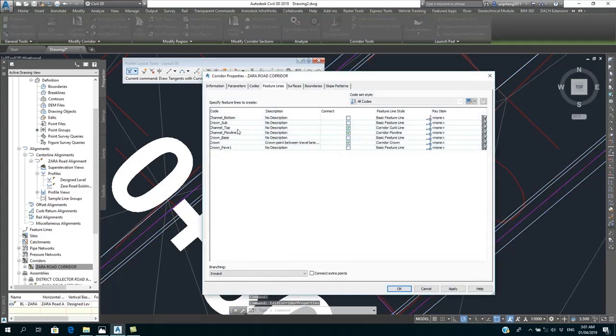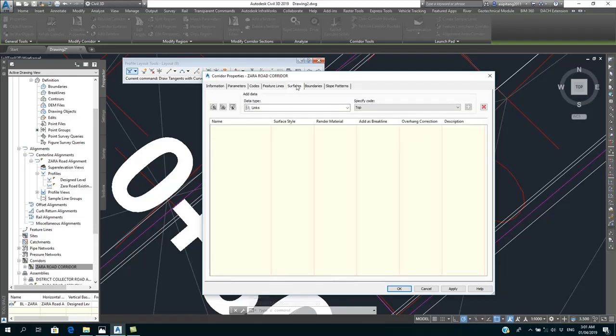While the end of the wall, if you say end of shoulder, you should not show the details, can show other details as well. So now after that, I can come to surface. You must create what we call the corridor surface, and you have to give it the projections. What projection are we using? You are using the datum, refining it to projection. So datum, in case you verify where you have to cut and fill, to take the datum information, the reference you're choosing in line with the existing condition.